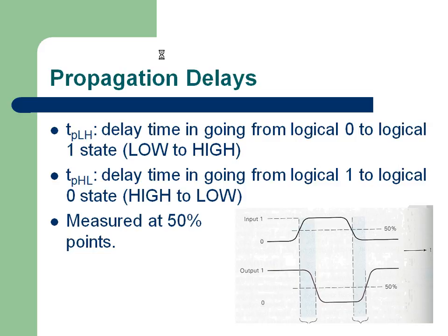You understand? So in our next module, where we talk about precise characterization of ASIC timings for sequential logic and all, for a gate we talk about two numbers. It may take any time between 5 nanoseconds and 10 nanoseconds to get the output. This becomes a major source of glitches in combinational logic circuits. We will study all about glitches, and there is something called contamination delay, all of that we are going to study. But the base for all of this actually comes from here. A fan out tells that, within some guaranteed amount of time T1, it can drive that many gates in parallel.